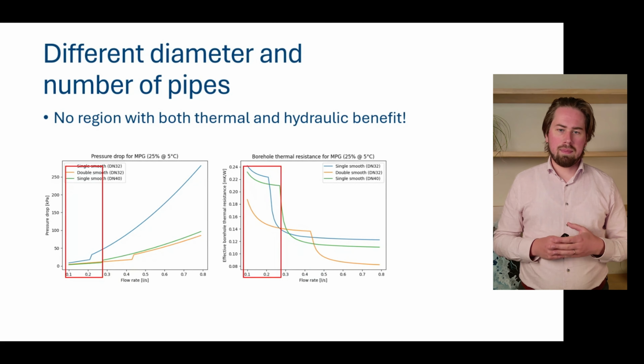And be aware that this difference in pressure drop, for very deep boreholes, 300, 400, 500 meters and so forth, can become really, really important in deciding which pipe diameter you have. And also your pump energy will play a role. To illustrate that, let's talk about this pump energy for a second, because having a larger pressure drop means that you will have more pump electricity consumption. You require more pump energy.